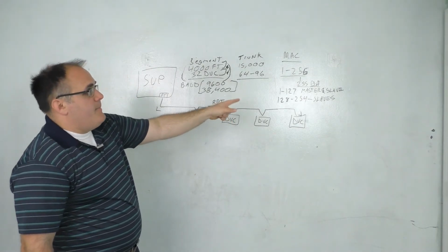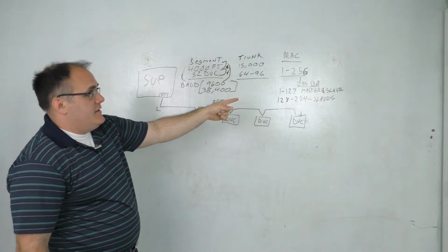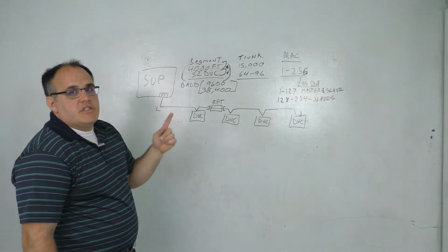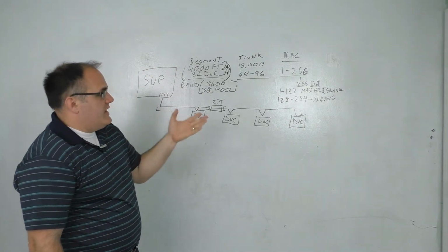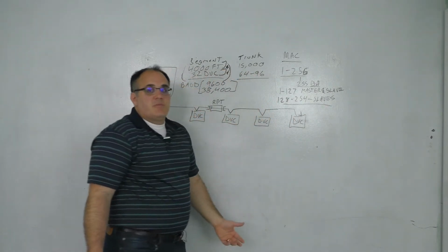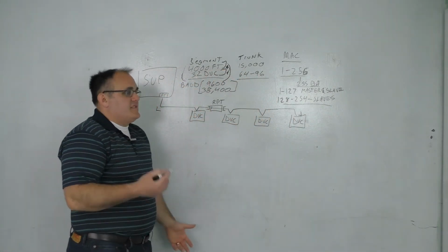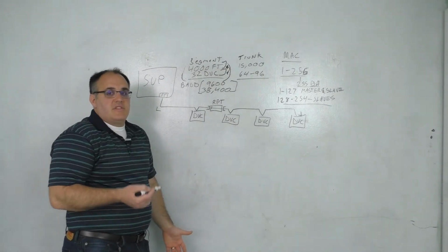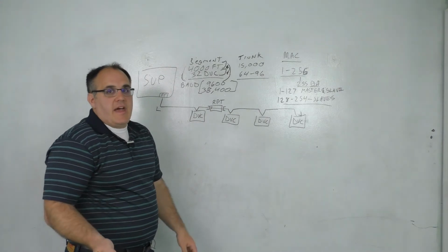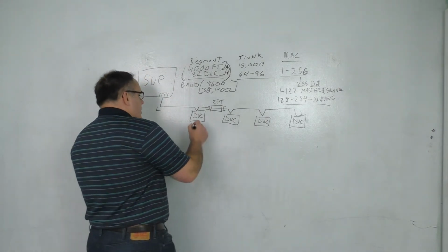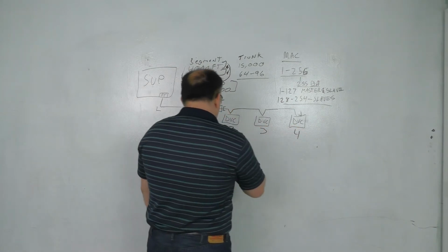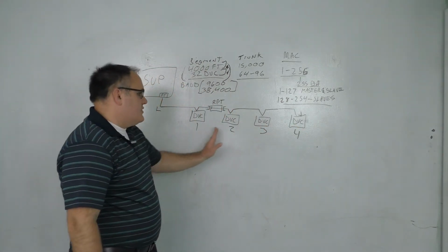Now, here's the thing. Masters can initiate services. Slaves can only respond to services. So it's not good to be a slave device because all you can do is respond. So typically you'll see master devices in most situations. Let's talk about addressing for a second. I mentioned sequential addressing is really good. What I mean by that is when we address, ideally, we'll address 1, 2, 3, 4, so sequentially.